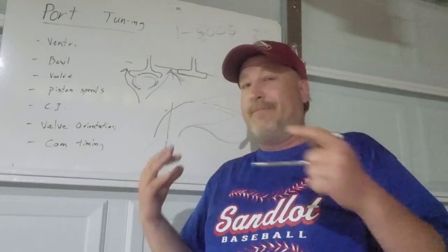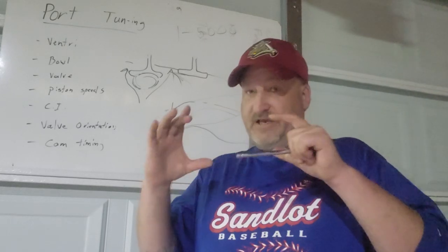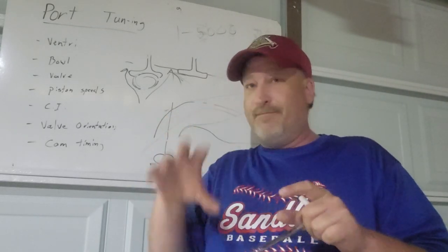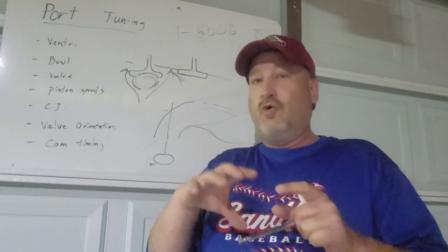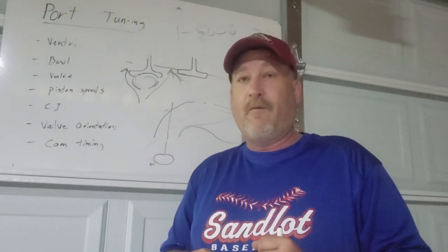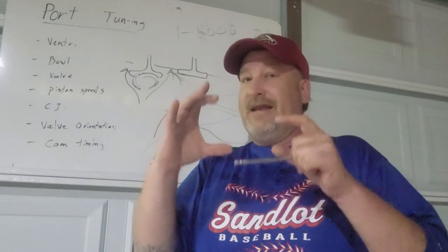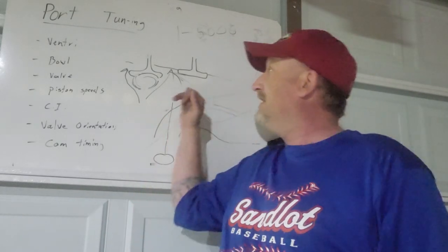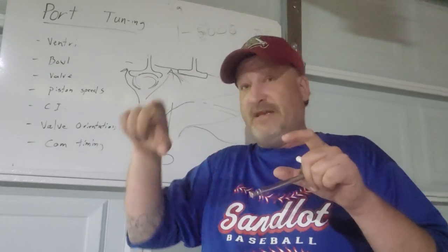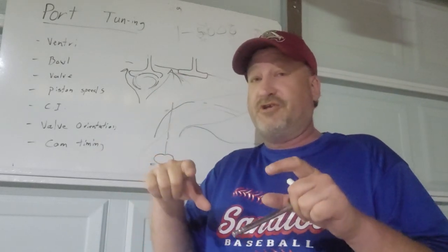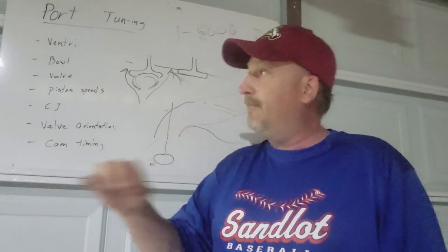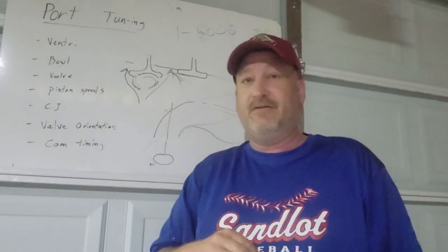But when you actually pop the cylinder heads off, the carbon print on your combustion chamber, if it's completely black, you're not achieving the proper port tuning. If you have a narrow carbon print between the intake and exhaust valve that's very narrow, and it doesn't include the entire perimeter of the combustion chamber, you know you have achieved premium port tuning.